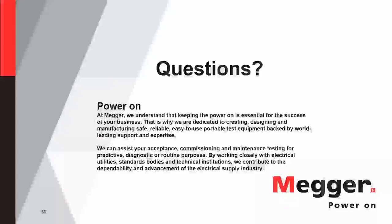The problem is this breaker's moving so fast, so it might only be a millisecond of difference, and we allow a couple milliseconds to change there. Usually like 2 in the open, and I forget what IEEE says, it's like 4 or something on the close.